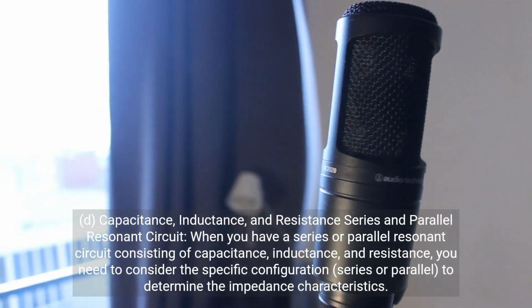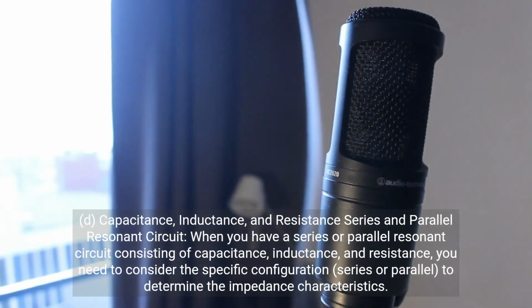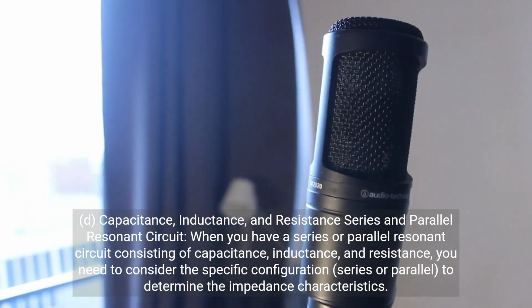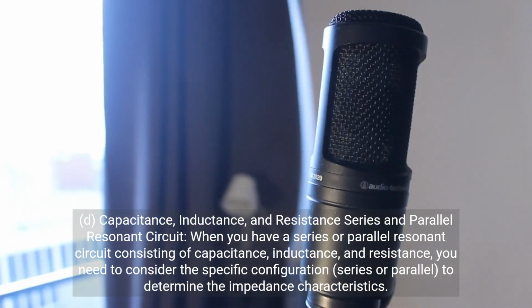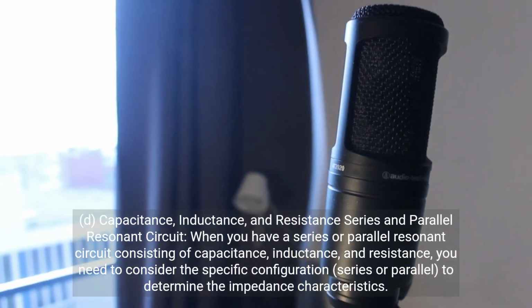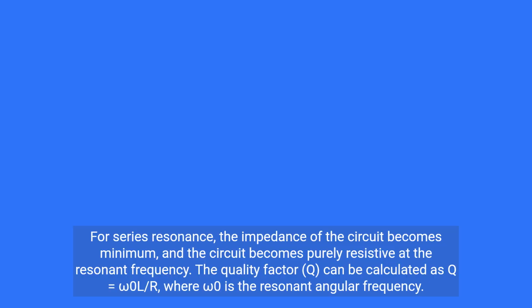D. Capacitance, inductance, and resistance: series and parallel resonant circuit. When you have a series or parallel resonant circuit consisting of capacitance, inductance, and resistance, you need to consider the specific configuration, series or parallel, to determine the impedance characteristics. For series resonance, the impedance of the circuit becomes minimum, and the circuit becomes purely resistive at the resonant frequency.